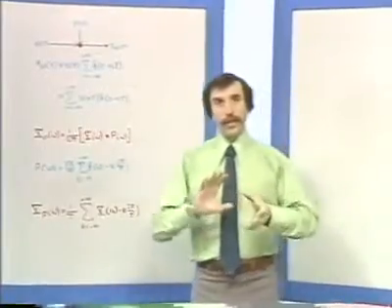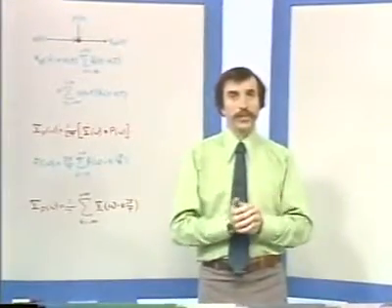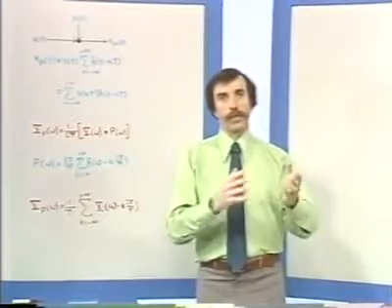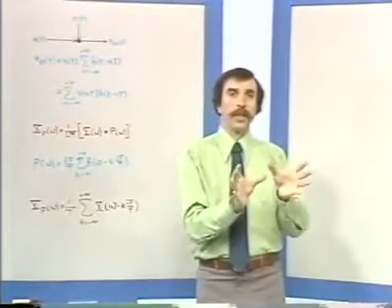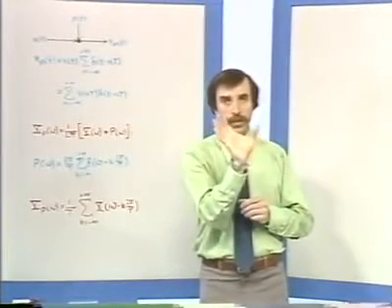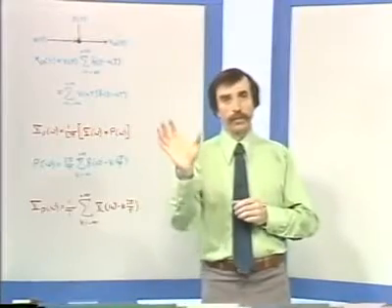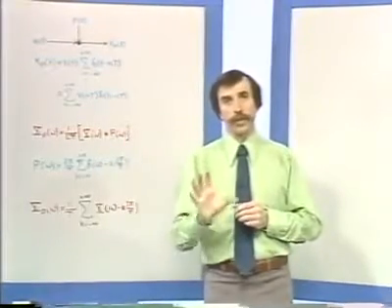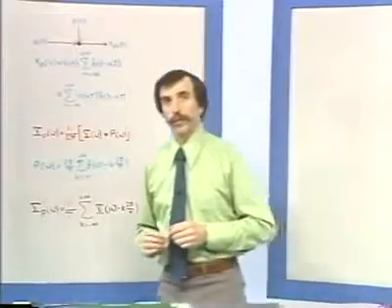So mathematically, that's the relationship. It essentially says that after sampling or modulation with an impulse train, the resulting spectrum is the original spectrum added to itself, shifted by integer multiples of the sampling frequency.